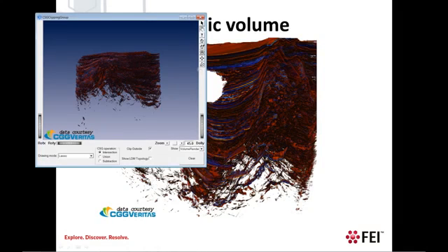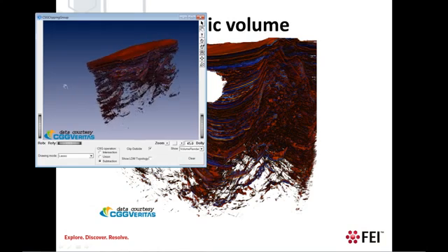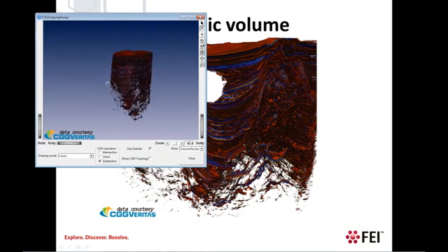But I could also very well decide to remove part of the volume. Following the same technique, I switch to the subtraction option and select part of the volume I want to remove. Finally, I can use the union to add another part.